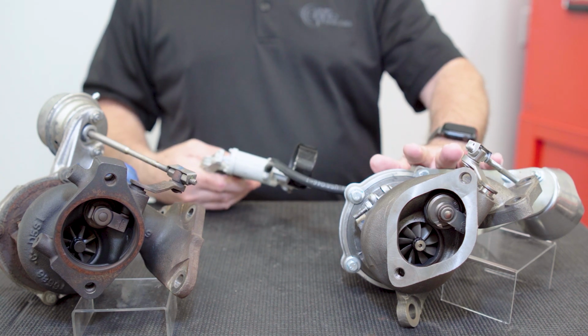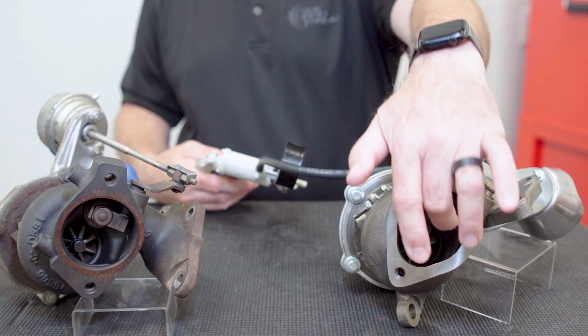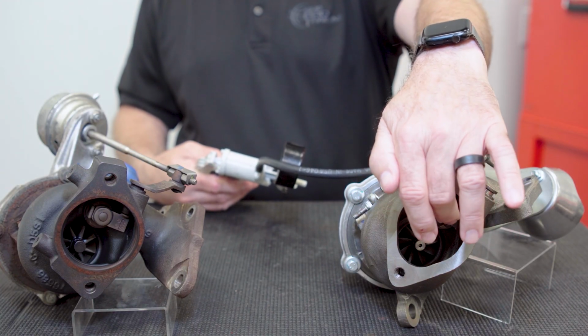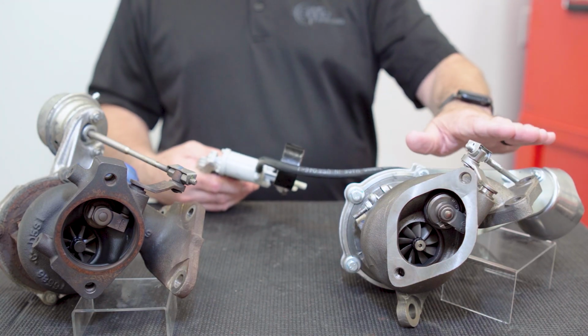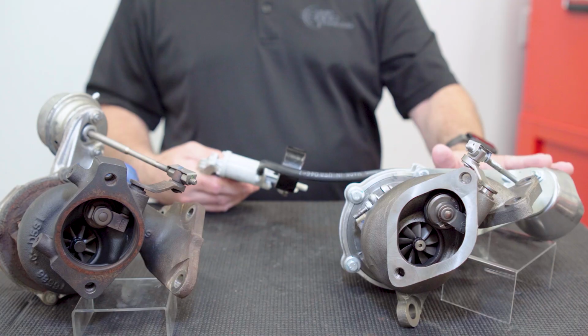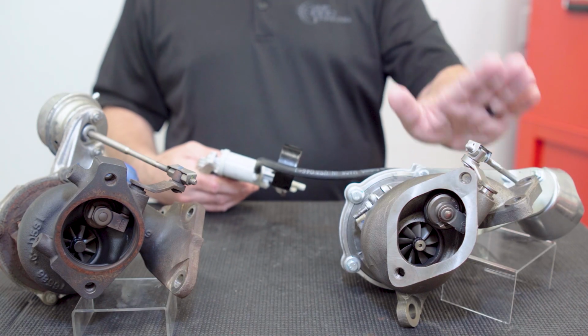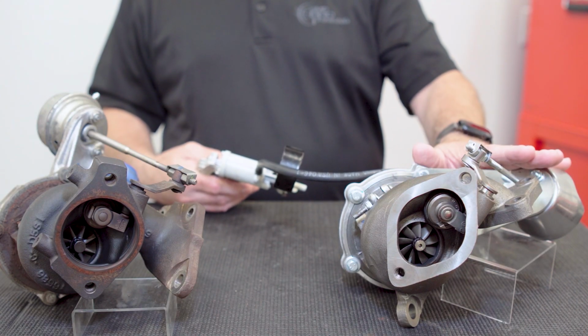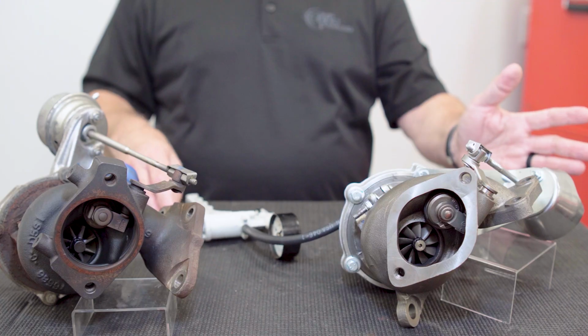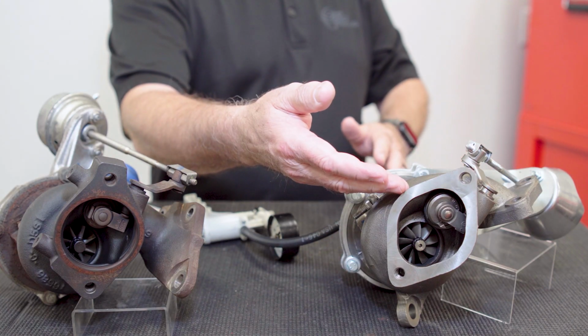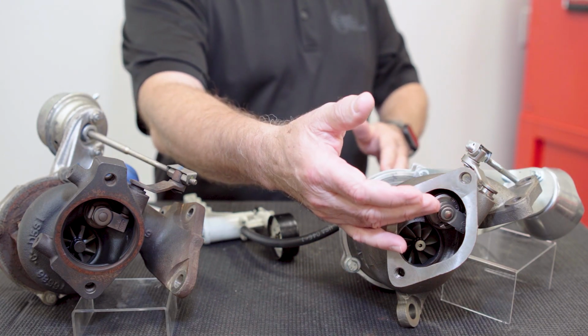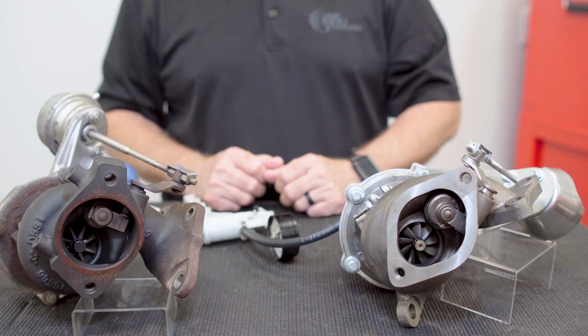Now this is still going to be on the vehicle, so you're not going to be able to see down in here the wastegate itself, but you can at least determine, okay, the wastegate actuator solenoid arm is all working correctly. Well, that's great, Mark, but what about the inside? How do we know if the inside is working? Well, this is where your scan tool is your friend.